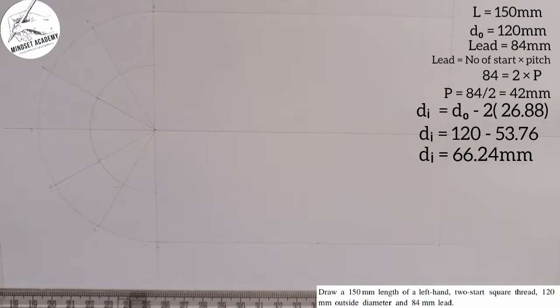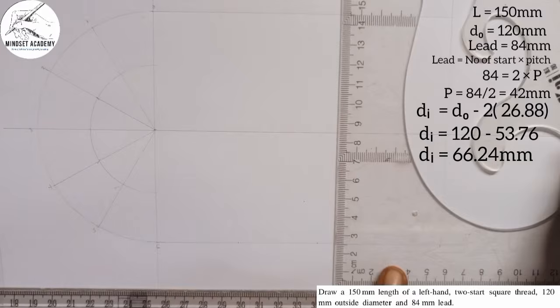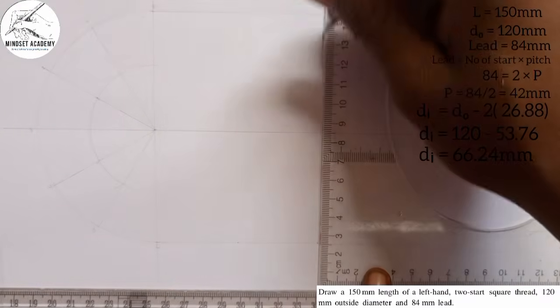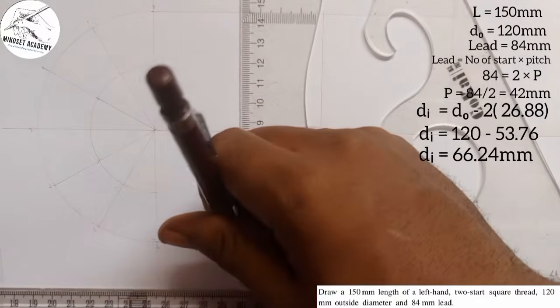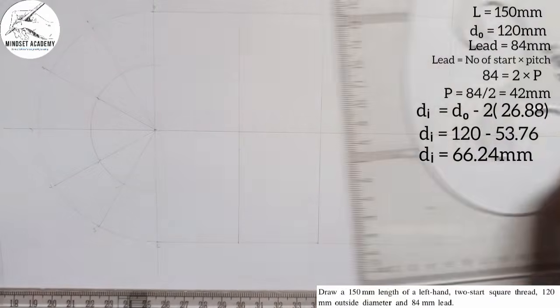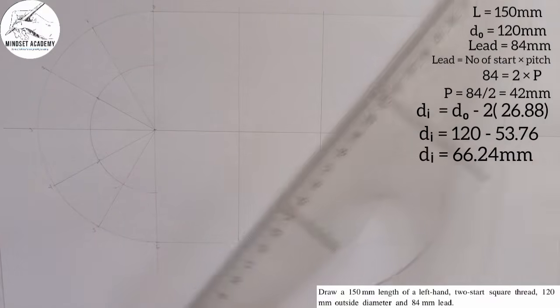Now the next thing I'm going to do is I'll project those points up. So when I project those points up this way, I'll have the first one, which is this, and the next point too, I'll project it up. And the next point too, I'm going to project it up. So this is what we have. I'm going to divide these 2 points into 12 and these 2 points into 12, right? It's easier instead of dividing everything once to 24. So I'll take them in different sections.